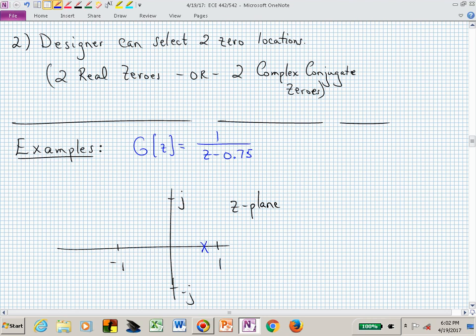What was the answer? I want a z-1 in the denominator, or I want to put a pole of my controller at z equal 1. And one way to do that, without even getting too complicated, is to just do a PI controller. A PI controller, and what would be an easy way to guarantee steady state errors of 0 and not have too complicated of a pole 0 pattern?